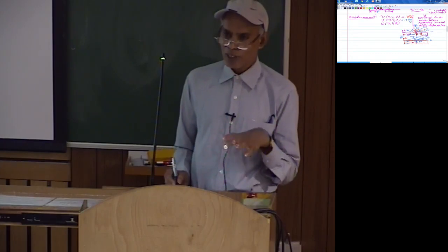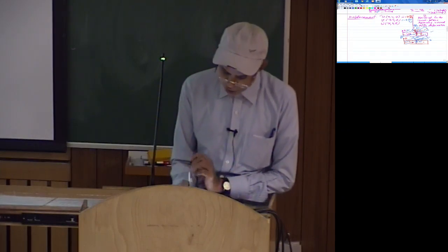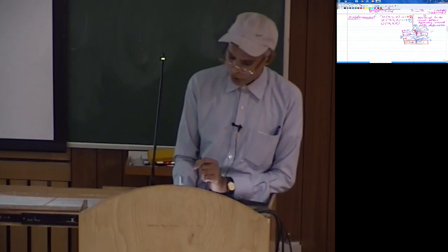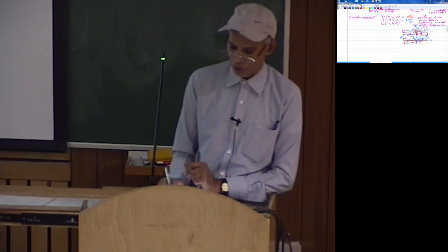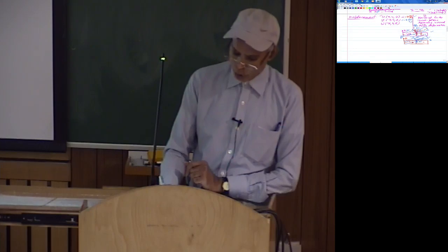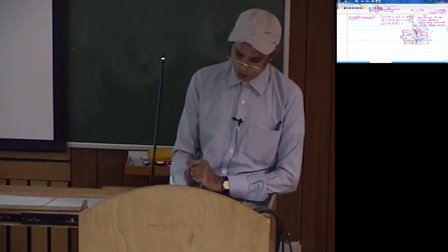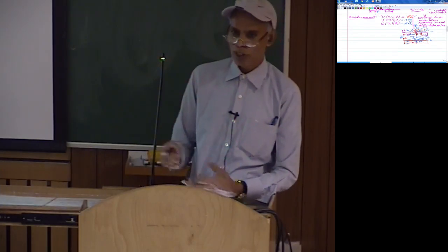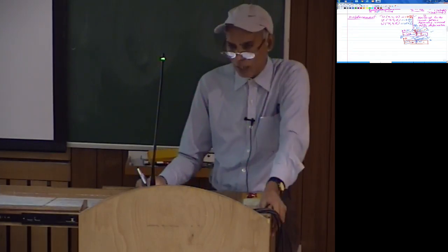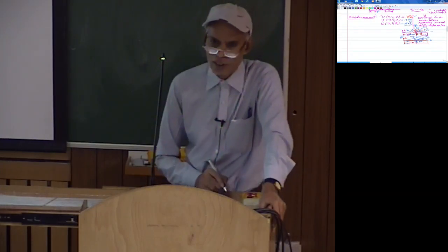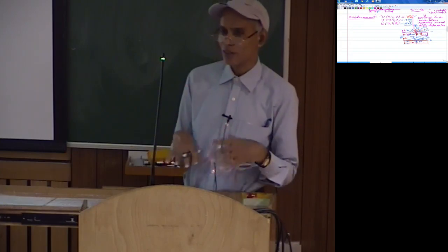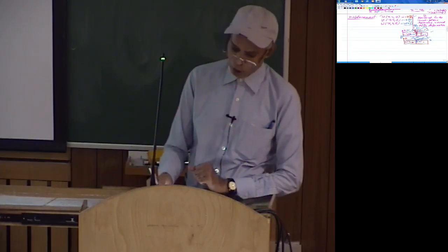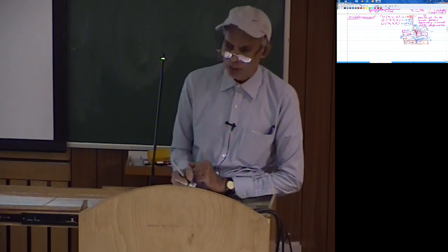So now what we have done is reduce our 3-dimensional problem to a 2-dimensional problem. Initially, in general for a 3-dimensional problem, u is an unknown function of xyz, and v is an unknown function of xyz. By doing this, we are saying that u is now a known function of z, which is linear in this case, and v is also a known function of z. In addition, we say that w is only a function of x and y. Of course, because of Poisson's contraction there would be some variation, but that is negligible. So we assume that w is only a function of x and y. In this process we are reducing a 3-dimensional problem to a 2-dimensional problem, and now we have one unknown function w, which is a function of x and y.